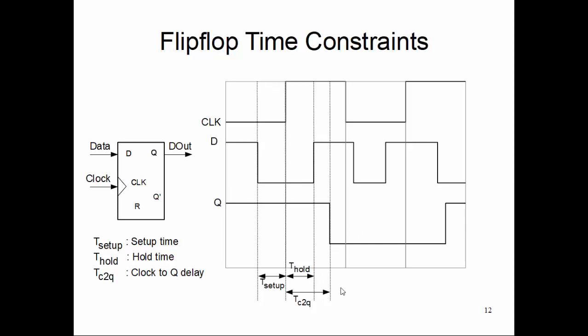Okay, that's just a couple of definitions. These are very important in the digital design area, and a lot of check analysis is done around this concept, whether incoming signals are meeting the setup time, hold time, and so on and so forth. And of course this clock to Q delay will impact the next stages of the logic, it will affect their setup and hold time. So that's another important concept here. But for you guys, these are the definitions, that's all you need to remember, that too for an interview if you go to certain companies which deal with digital design.